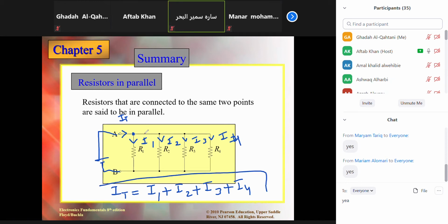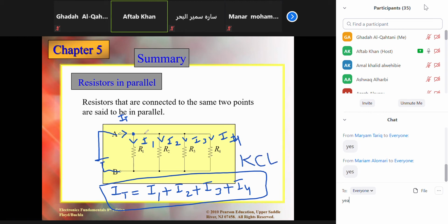So you know which law this is? This is a rule which we call Kirchhoff's current law, which says that the current meeting at any node or junction, as I said, you can use it at any point, at any junction, is basically the sum of incoming currents is equal to the sum of outgoing currents. So basically, as I said, this is a single line. And I'll also draw another example with this picture, which could also be considered this way.